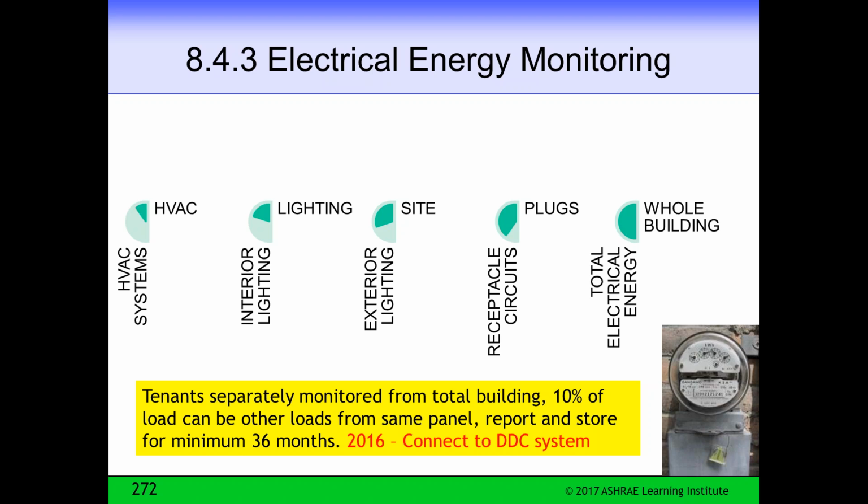but the wire management that he's going to get out of adding that panel, and what he pulls out, and what future people do, and what you would do as you came back to a building doing a site survey, is going to be tremendously helpful, because what we've asked for is for the HVAC systems, the lighting systems, the site lighting system, the plug loads, and the whole building all be monitored separately. So you'll have a meter for the HVAC, you'll have a meter for the lighting, you'll have a meter for the site lighting. And how you do that, how you collect that, will cause you to separate certain loads probably.